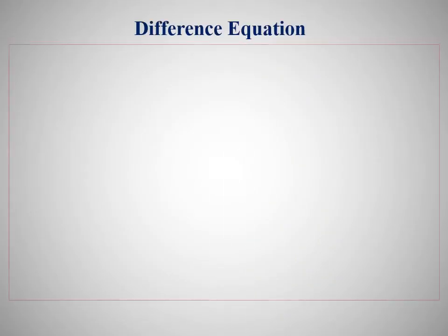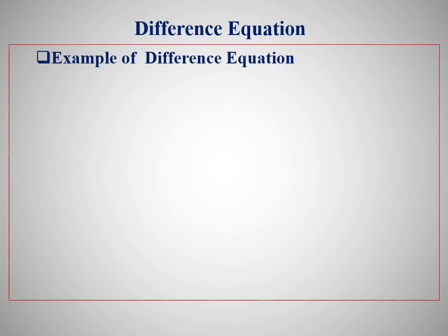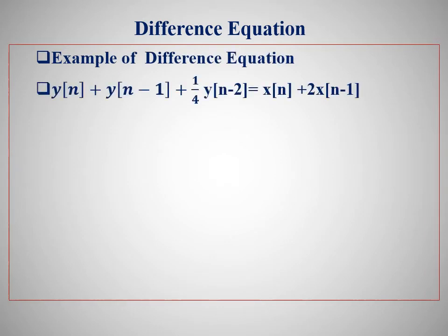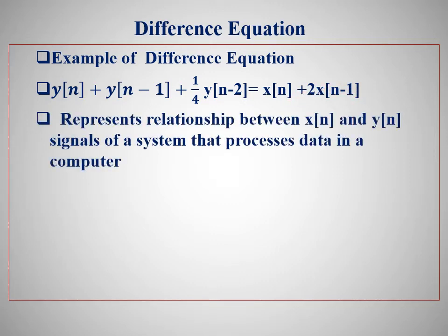Next, let us go on to the difference equation. The example of a difference equation is y[n] plus y[n-1] plus 1/4 y[n-2] equal to x[n] plus 2 x[n-1]. This particular difference equation represents a relation between x[n] and y[n] and is helpful for processing data in a computer.